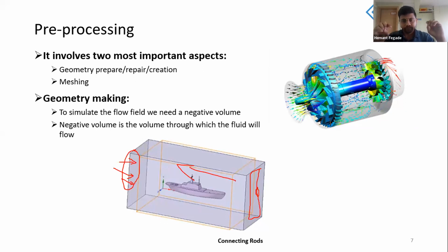That is why we will be including that into the internal flow regime, or basically we are going to consider the surrounding casing as its enclosure or as its domain. Basically, we are going to limit that part over there. So essentially, when we are constructing a geometry, when we are preparing a particular simulation, all of these factors we need to understand and consider before actually going into the simulation.